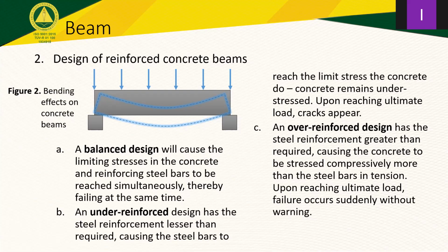And this is a good indicator that the building is still being supported by the steel and the concrete, by whatever is remaining in there. It avoids accidents because the failure can be addressed by improving on the design, or remedying the cracks. Unlike when it's over reinforced, the failure just happens suddenly.